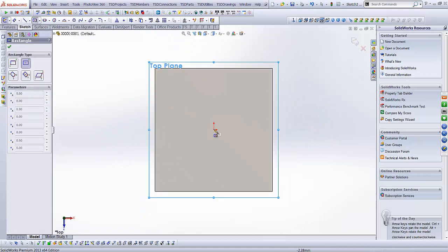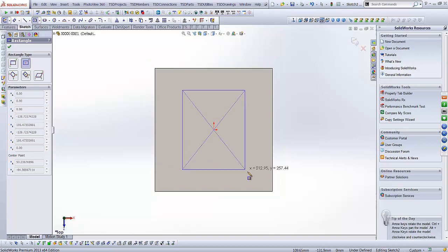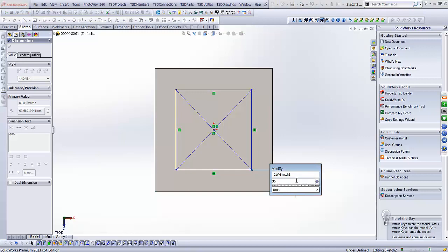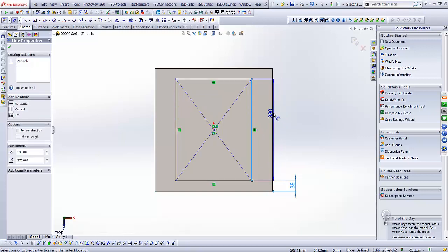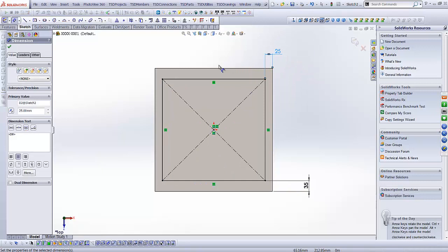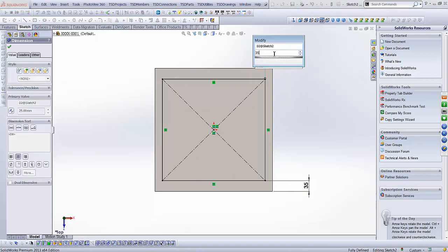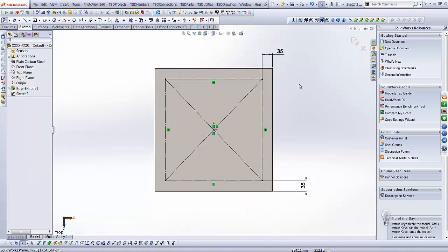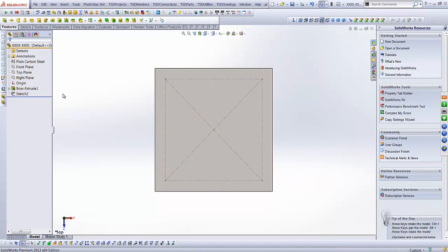So we can do another sketch, and you can select the same import, same origin, and same rectangle. In here I'm just adding dimension clearances that I can change at will at any stage. And what I usually do, we stick with 35 edge clearance there, thanks. And what I do is I make it all for construction. Okay, so there's no lines or anything. So I've got myself a plate edge, and with that I can name my sketch by clicking on it, center hole sketch. Okay, so that sets up my holes.